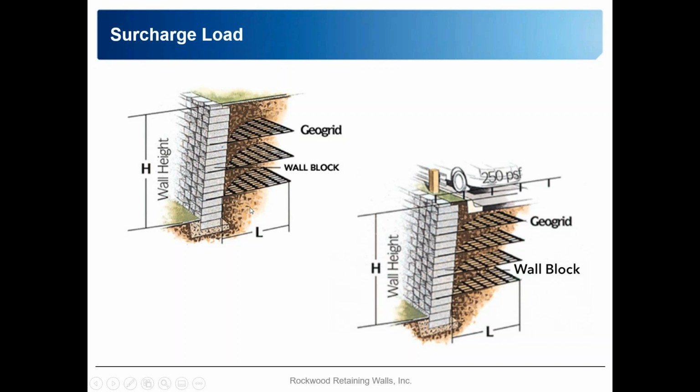And the reason I say that is, the block, say a classic 8 unit, is 12 inches deep. The geogrid is going to fit into that block a foot. That really only gives us about 3 feet from behind the wall that we're reinforcing. So just a rule of thumb on those design lengths.